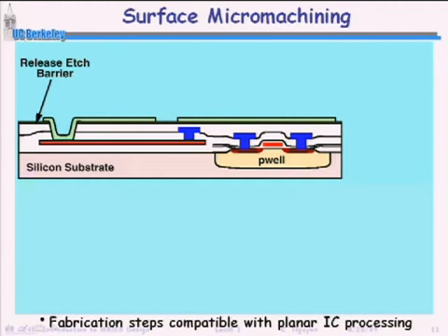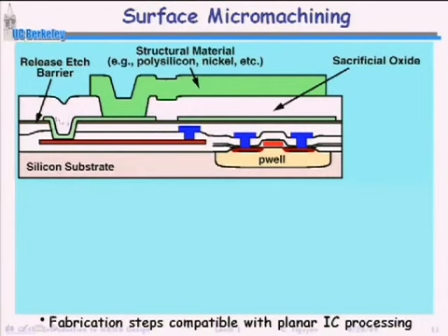And once you've achieved this cross-section, the final step is to put this into hydrofluoric acid solution, which will remove the oxide preferentially, not attack the polysilicon or the nitride above this here, and leaving you then with a freestanding beam. This is the process that is used, I guess, for a large fraction of the MEMS products that are out there. Okay, very simple process.